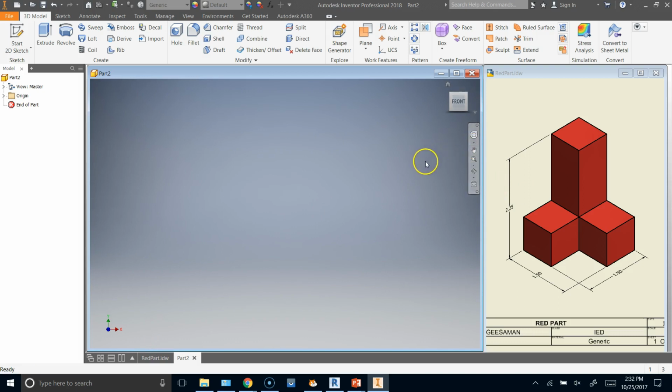And I am going to now draw a rectangular prism with these 3 height, width, and depth dimensions. Now, I'm going to draw from the front view. And in the front, I see height and width, which means I'm going to draw a 1½ inch wide by 2¼ inch high rectangle. I could do it from the right, where I see depth and height. I could do it from the top, where I see width and depth. That will only define what the size of a rectangle is. So let's go from the front.